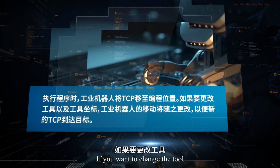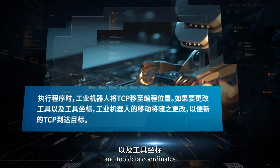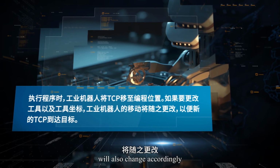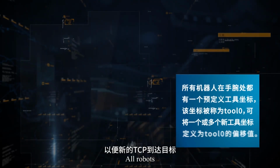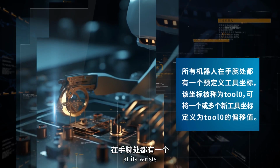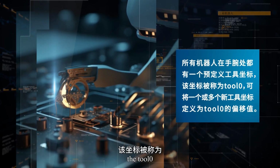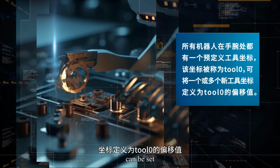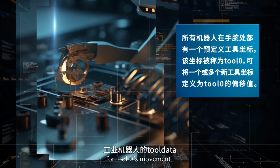If you want to change the tool and tool data coordinates, the movement conducted by the industrial robot will also change accordingly. All robots have a default tool data coordinate at its wrist, which is called tool 0. 1 or more new tool data coordinates can be set from tool 0's movement.